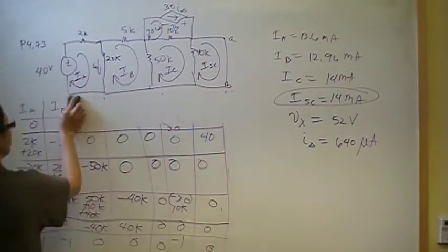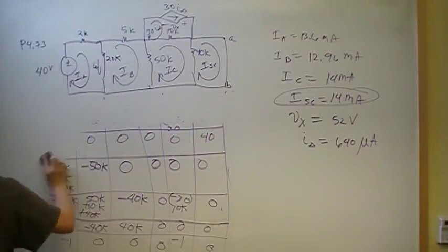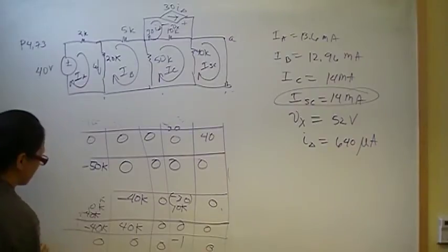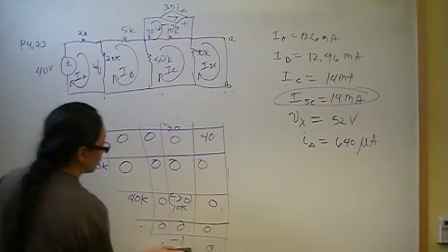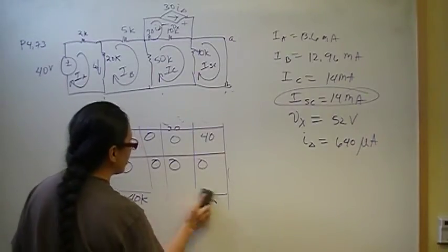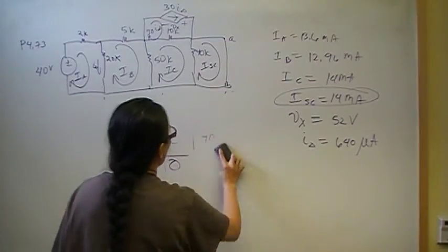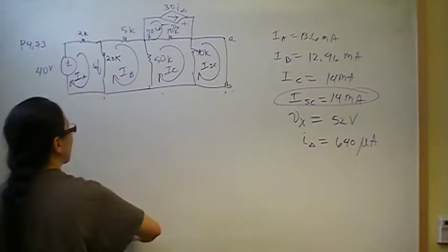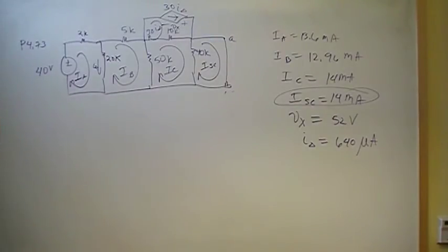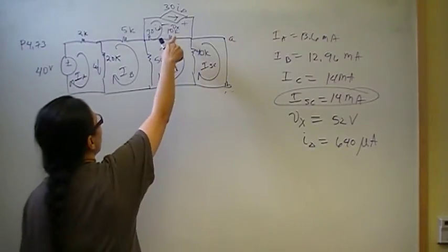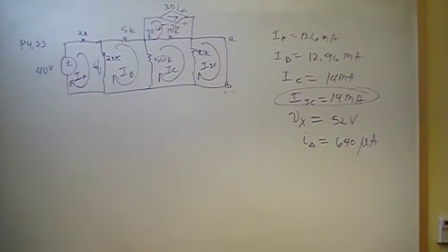The second half is the Thevenin resistance. Now, we would really like to just be able to disable the power sources and then see what resistance is seen by the load. But we can't do that, because it only works with independent power sources. When you have a dependent power source, it does not work.